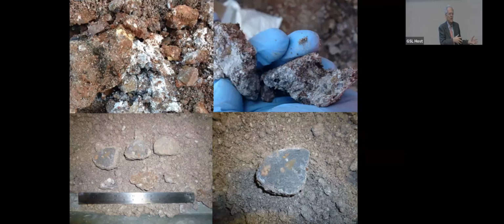That methane generated by the void former, in that project they sank a shaft adjacent to the building and tunneled underneath to remove the slab. They might have had to do the same in Cambridge if we'd known it could have been there, but we didn't. So the aluminium is a major potential risk. Also, it can cause a heave when it reacts.